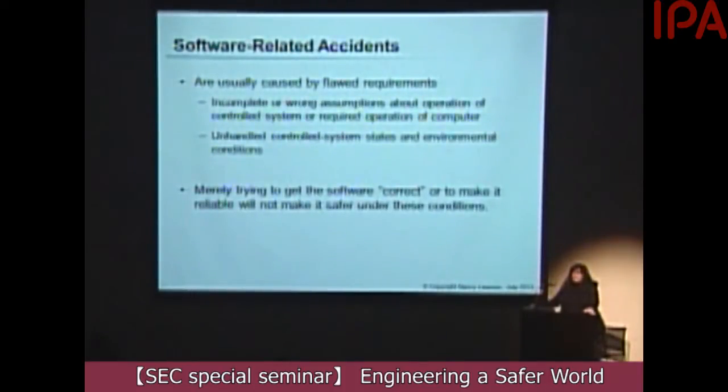Now, the engineers probably didn't bother to tell the software engineers about this because the software wasn't supposed to be executing then. But the software engineers decided to be more efficient and start the software early in order to even the load on the processor. So the software was running, it thought the spacecraft had landed, and it turned off the descent engines.